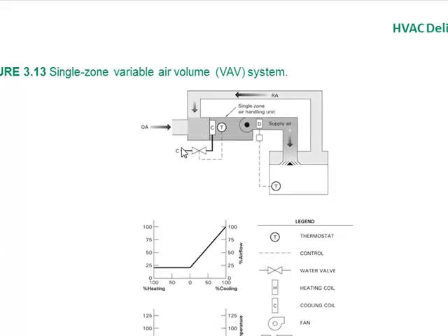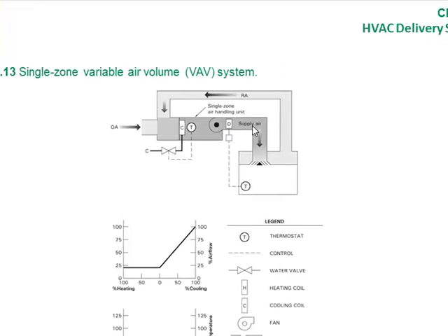In this one you have a cooling coil. And this thermostat here inside the duct in this situation controls the cooling coil. So the outside air blows over that. Then you've got the damper, which can control the airspeed. If you don't like a drafty area, you can close that damper off and it won't blow so hard. So that's how they would control the temperature in this room, because this only has cooling in this particular system.